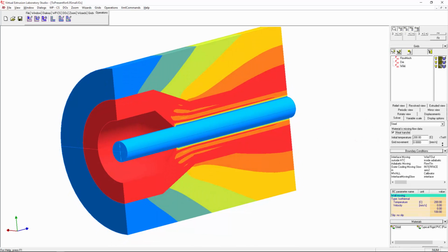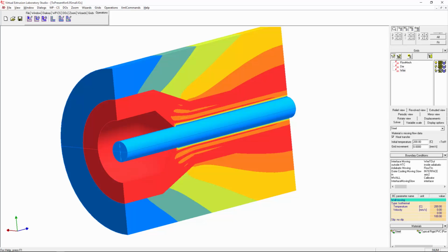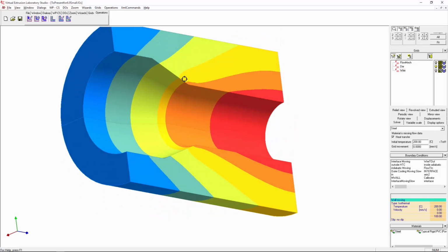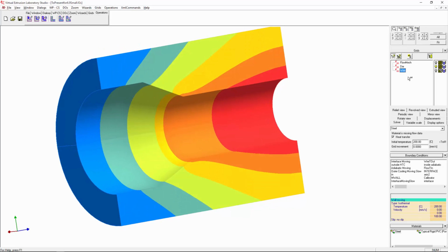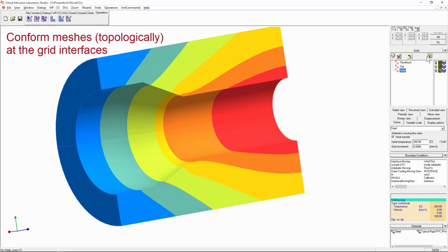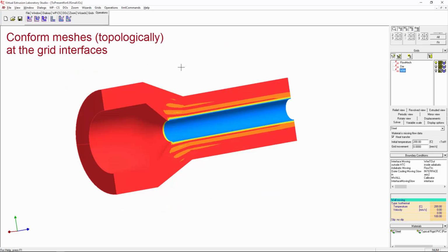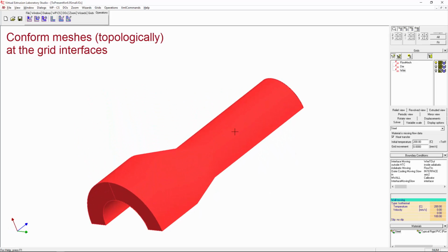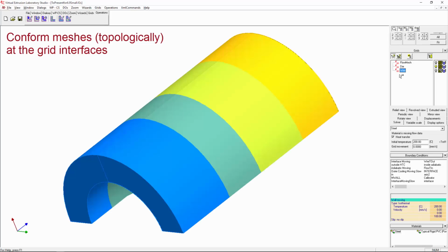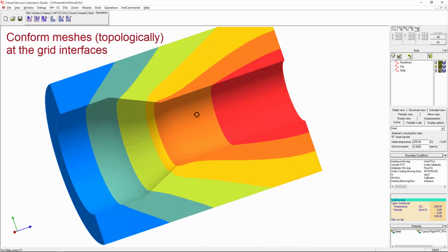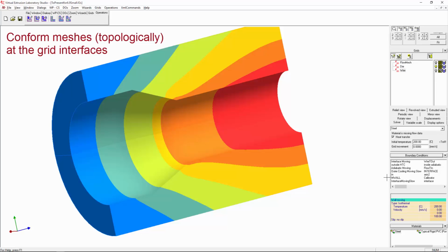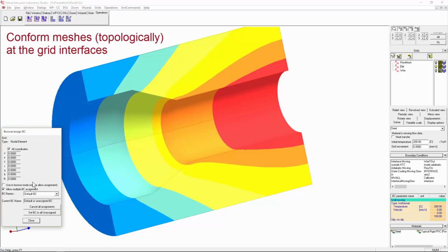So we can see that these are quite interesting, and we also have an outer body. When we solve it together, this outer body interacts with the flow mesh, and it interacts because the triangles on this body, if I showed you the triangular mesh, you would see that it is exactly as the flow mesh. So to be able to do this, you need to have conforming meshes. On this surface, the elements need to be exactly the same as the elements on that surface. And what's more, you need to put there a special boundary condition, which is interface.